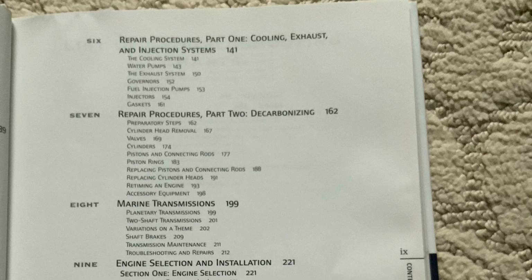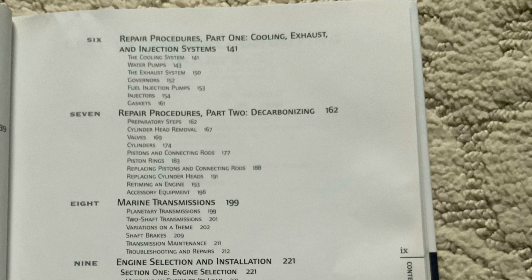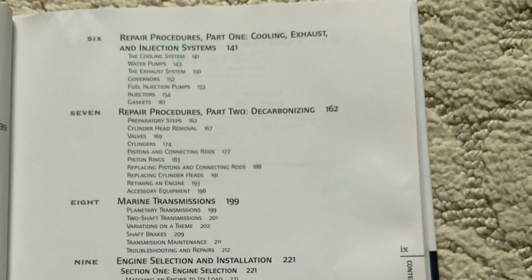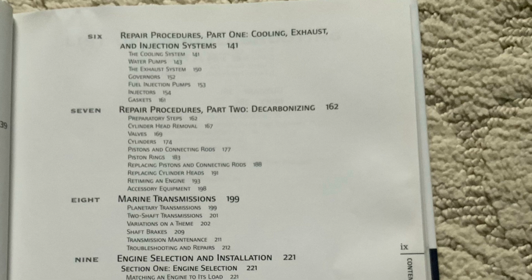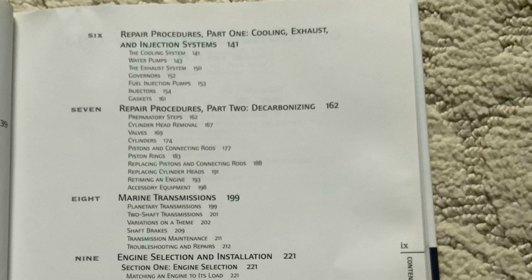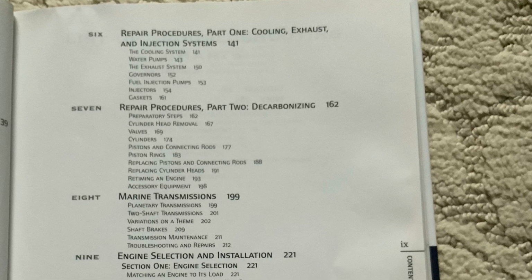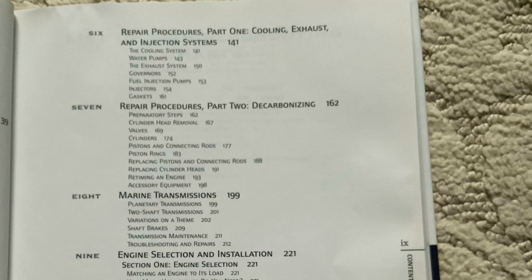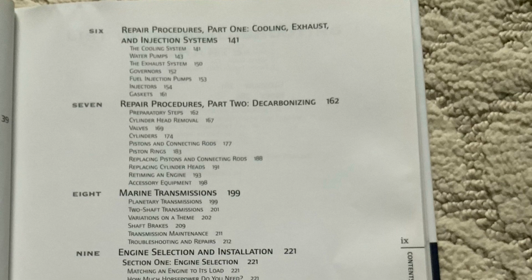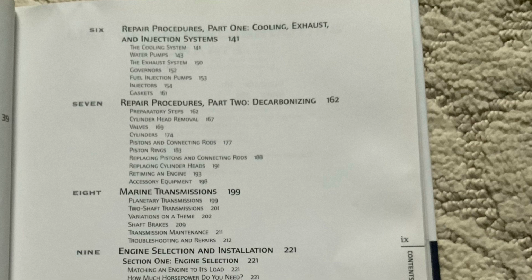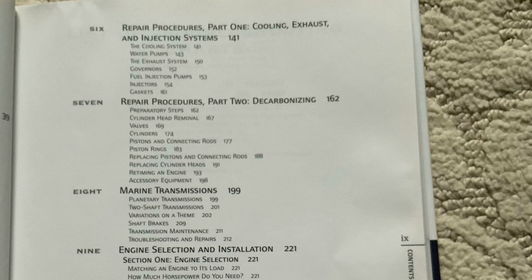This is what happens during ignition in an internal combustion engine. A body of air is trapped in a cylinder by a piston and compressed. The temperature rises. Fuel is introduced by some means and ignited. The burning fuel raises the temperature in the cylinder even higher, and this raises the pressure of the trapped gases.